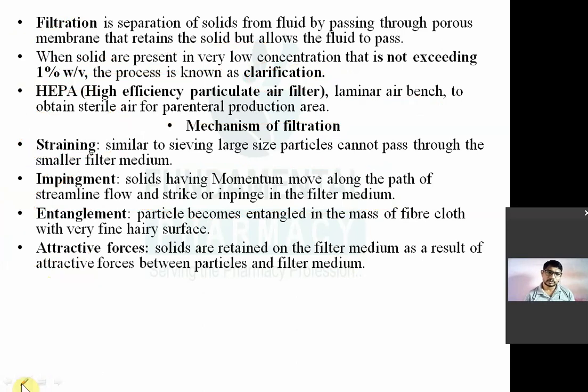Okay, so they may ask you a question like this: one of the following is not a mechanism involved in the unit process filtration. They may give you a few of these options, and they may give another option which is not present among them, like straining, impingement, entanglement, and repulsive forces. So you should be able to answer that question. The mechanisms of filtration are the four: straining, impingement, entanglement, and attractive forces.